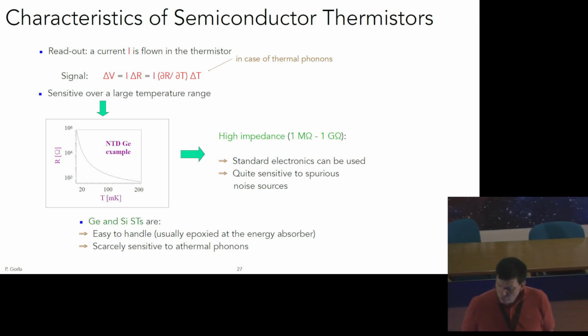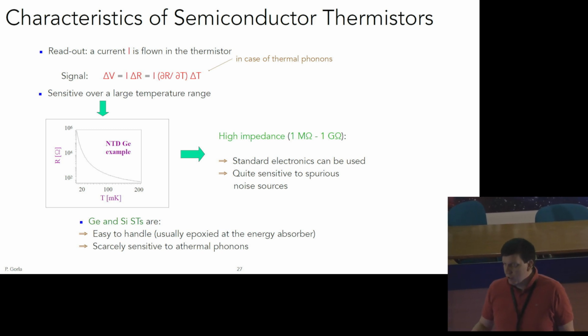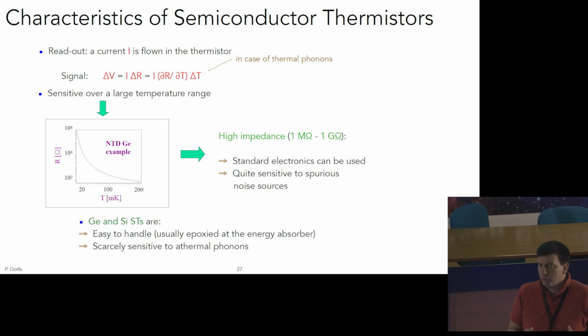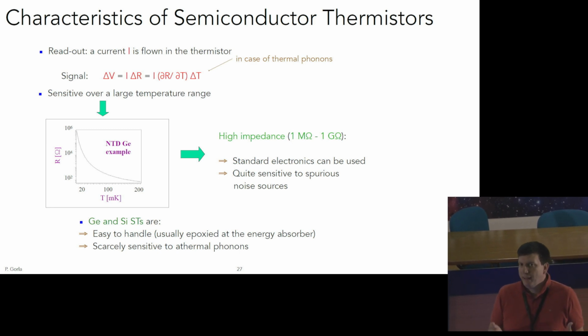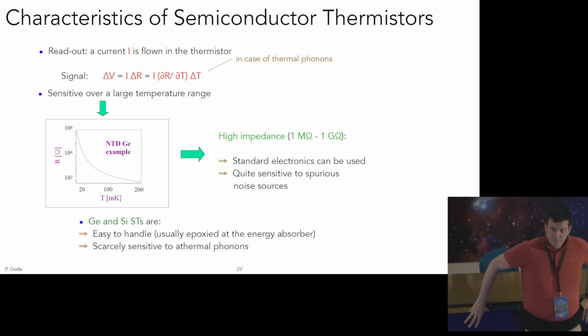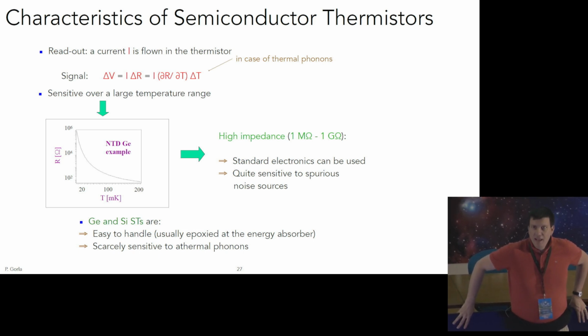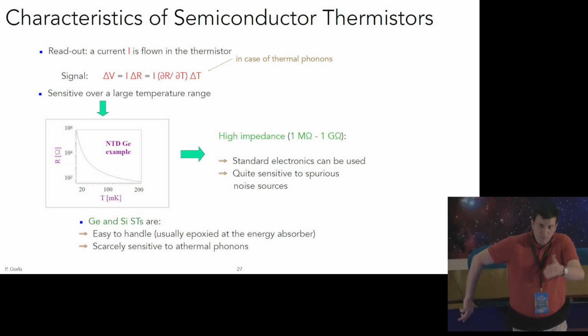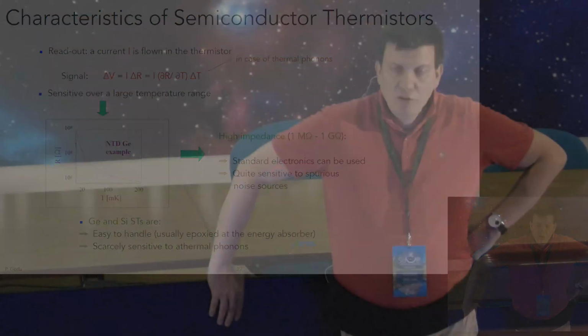so the issue with neutron transmutation doping is you expose this sample to a strong neutron flux. What you get is basically mostly neutron capture. So you produce some specific isotope that is decaying. So you typically, in case of germanium, produce germanium isotope with a higher number of neutrons, which eventually undergo beta decay or electron capture and produce your dopant.